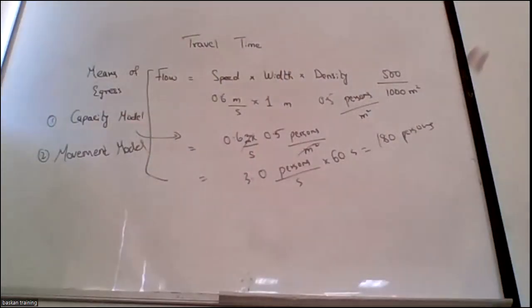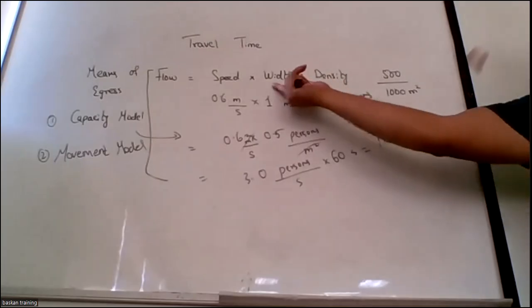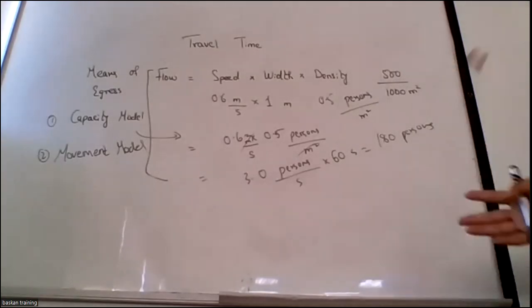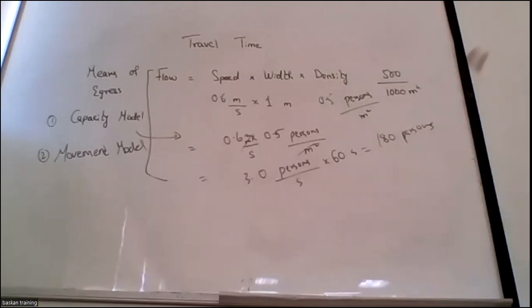Movement models are usually defined, or can always be calculated, in those occupancies where I have too much crowd, where I cannot focus people on one width of a corridor. For example, if there is any type of threat in Global Village, whatever means of exit I have, I want all the people to evacuate. I will open all the pathways so that the maximum number of people can evacuate. But how many people can one door occupy, that I need to know. That is the movement model.